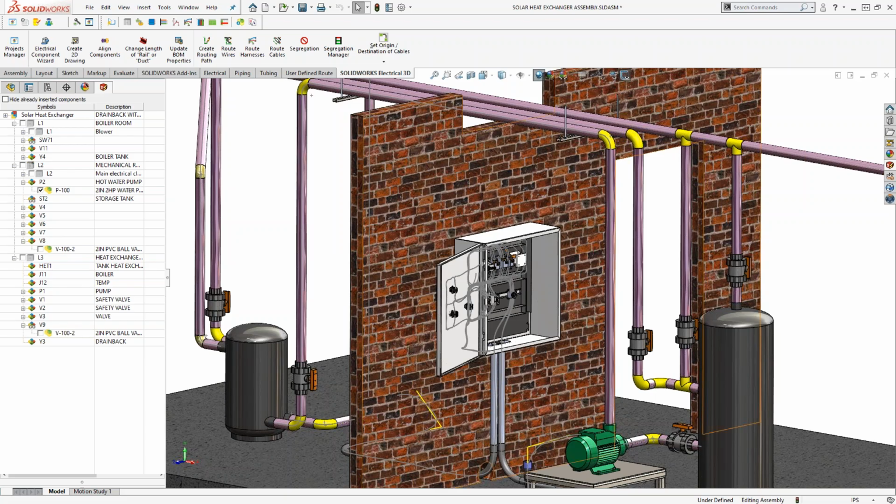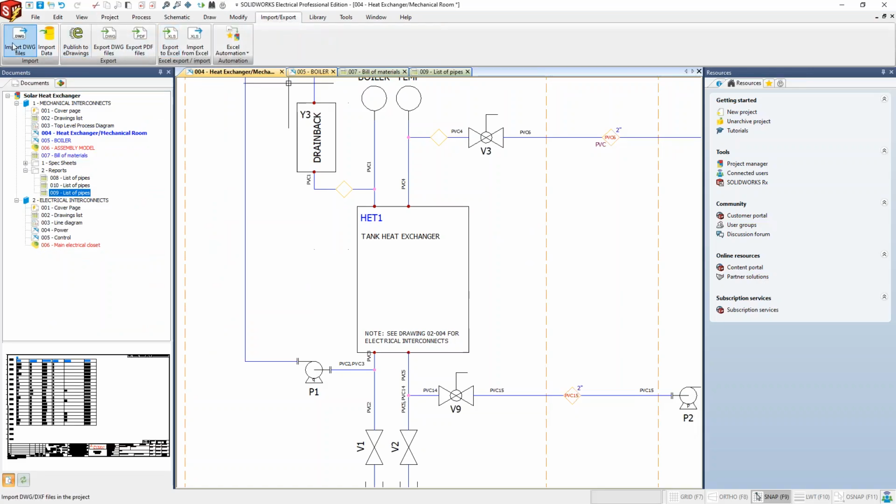Right now, you have the ability to import that information. You do have the ability to import DWGs. We talked about importing symbols earlier. You can also import data from something like Excel, right? So if you have a parts library that you want to import, again, it's a wizard that we would run through, and you essentially map out and tell the software, this is my manufacturer parts part number column. This one here is the actual manufacturer part name, and so on and so forth. So you would run through this wizard to add that information to your library. Hopefully that made sense.